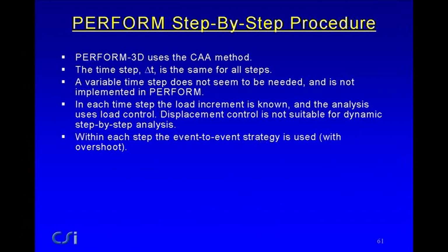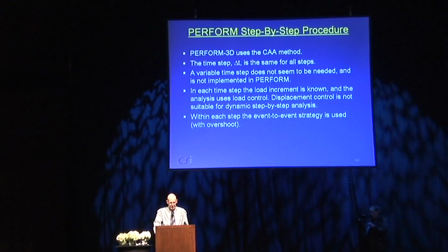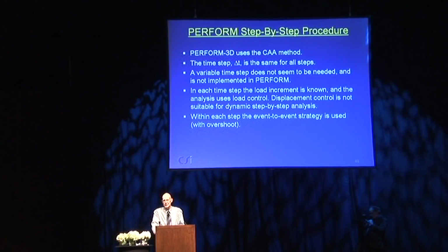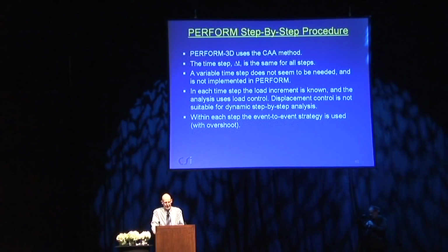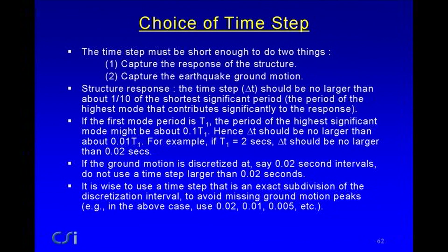In each step, it uses load control for the load increment. We discussed previously using displacement control for pushover analysis. It's better for pushover analysis than load control. You can't use displacement control in dynamic analysis. You must use load control. And then within each step, it uses the event-to-event strategy. So it's event-to-event strategy with load control for dynamic analysis, and event-to-event strategy with displacement control for pushover.